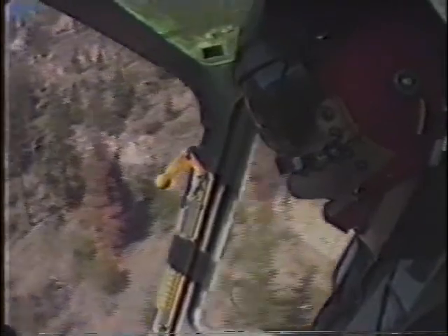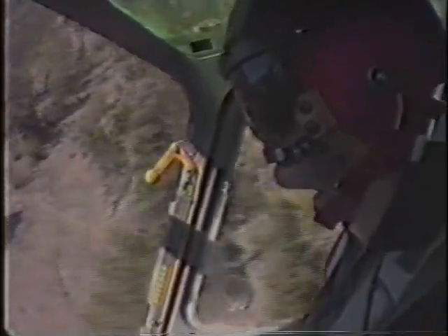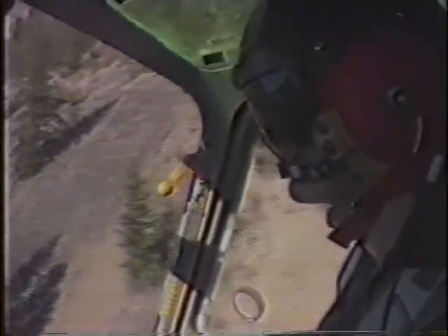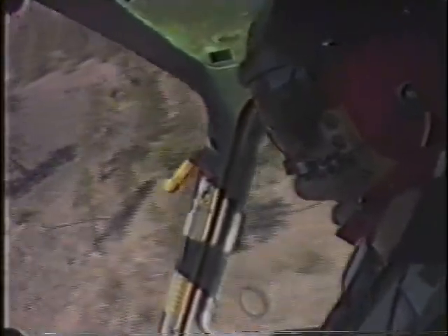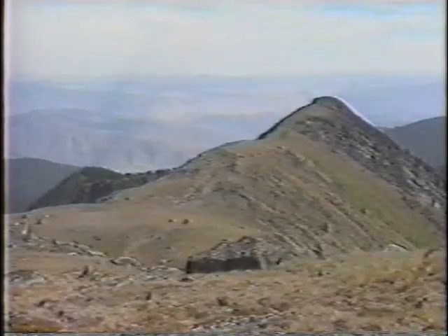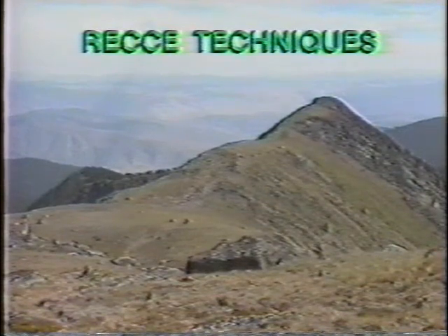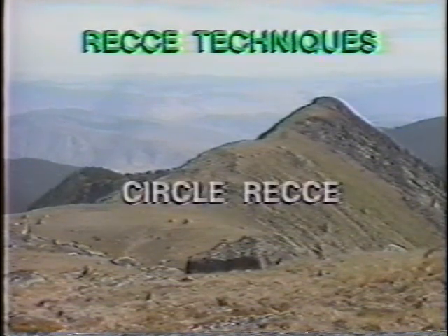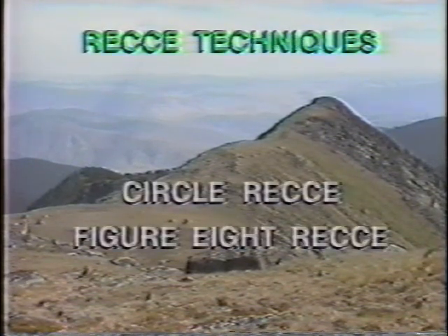That means tucking in tight to the hill, as close as one rotor blade away to stay in the boundary layer, and maintaining a constant altitude 50 to 100 feet below the top of the mountain. Here you're sure to be below the demarcation line and can get a good feel for the actual wind conditions in the area. We then employ two types of recce techniques at eye level to assess the LZ and the winds at that altitude. They are the circle recce and the figure 8 recce.